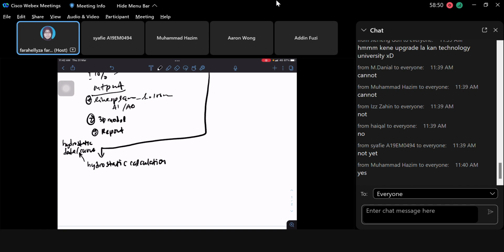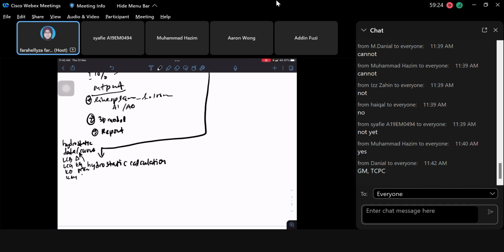I hope you still remember last time you had different graphs, so different hydrostatic data. So all this hydrostatic data: LCB, LCG, KB, KMT, displacement, what else? KG, what else can you get? MTC, moment to change trim per centimeter. What else? What else hydrostatic data do you have? TPC, GMT, yes, right? And the rest.